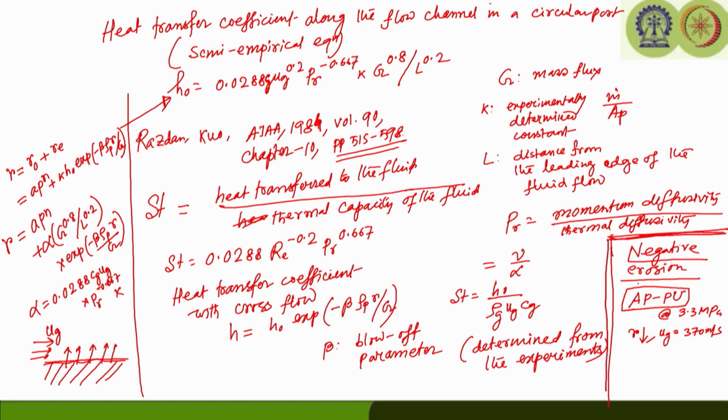What we have told so far, that only erosive burning gives an increase in burning rate, is not true. For a certain combination of oxidizer and binder, at a particular pressure and with cross flow, the burning rate can decrease for a certain cross flow velocity, but once we increase it further, it can increase again.